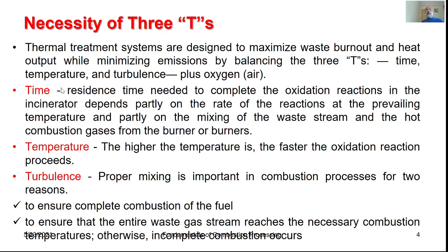The time is the residence time needed to complete the oxidation reaction in the incinerator, which depends partly on the rate of the reactions at the prevailing temperature and partly on the mixing of the waste stream and the hot combustion gases from the burner or burners. The second T is temperature. The higher the temperature, the faster the oxidation reaction proceeds.